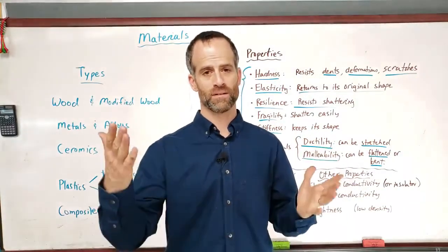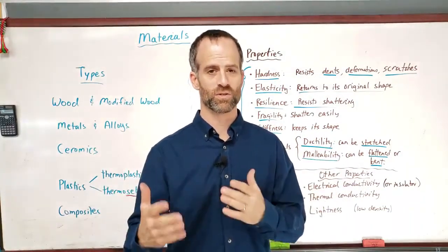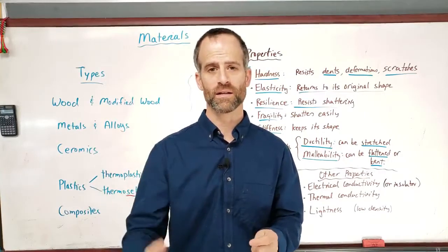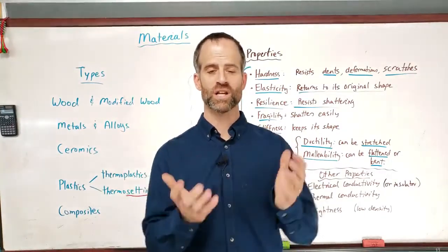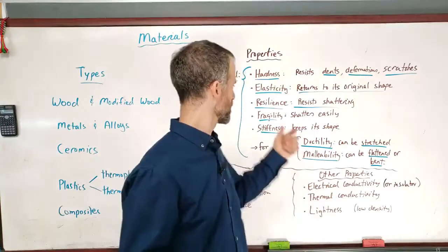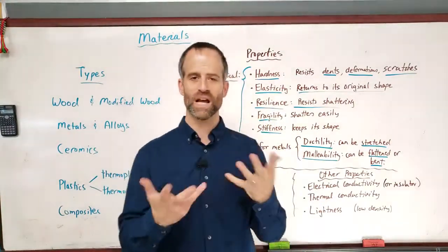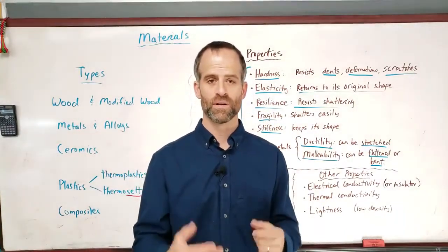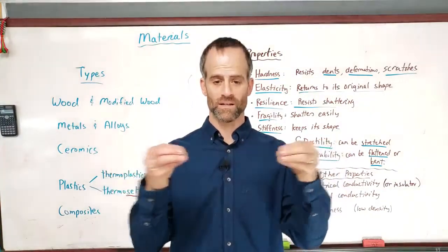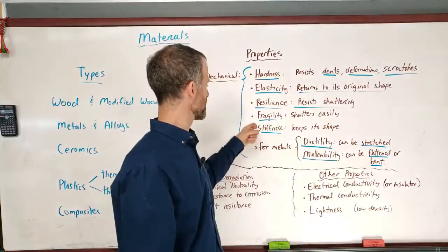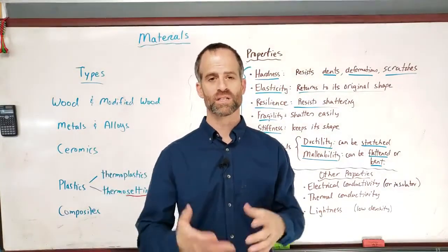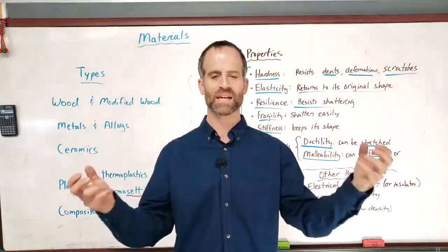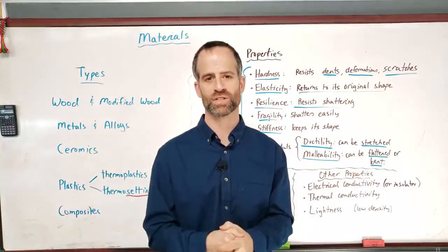If you temper it a lot, you can basically make it so that it can change its shape a lot and it won't be fragile, it won't shatter. For example, if I want to make a spring, I want elasticity for my spring, so I would temper it more to get rid of that hardness so that it can actually get deformed and take its original shape back.